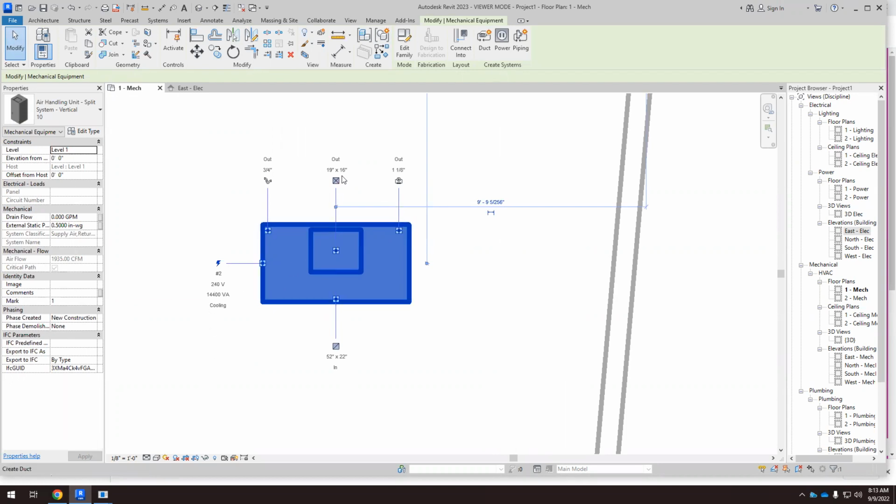We have information about when we have a square like this, it's a duct. So if you hover your mouse here, you see that you can create a duct. So we have a duct here and we have a duct there, create duct. This is in and this is out. Okay, important. If this is in, it means that this is an inlet, so the air goes in this direction. If this is out, it's an outlet, the air goes in the other direction.